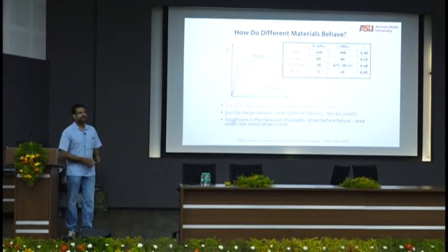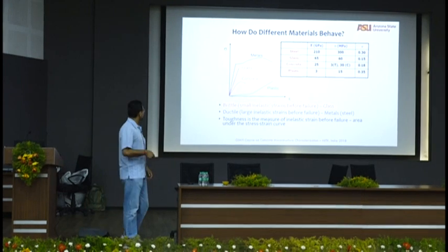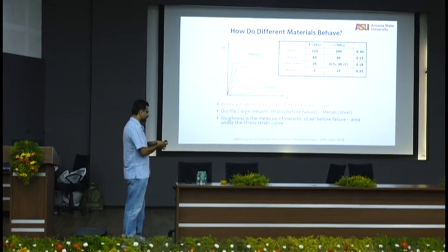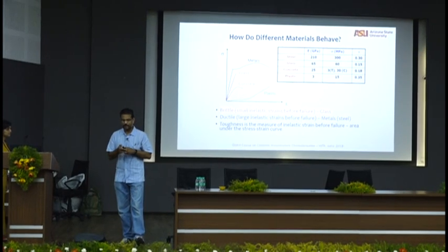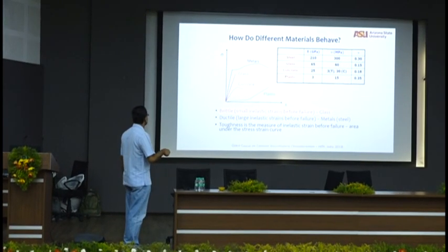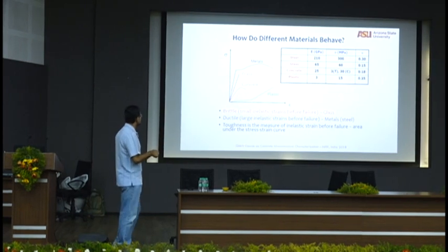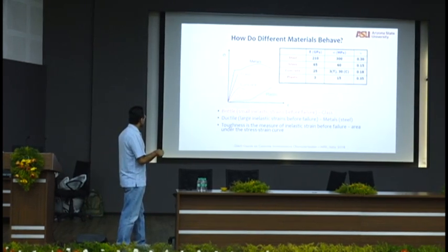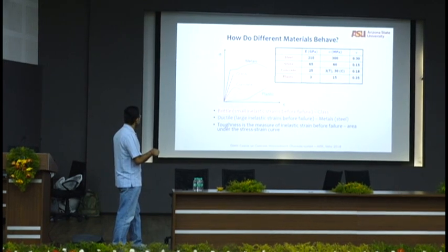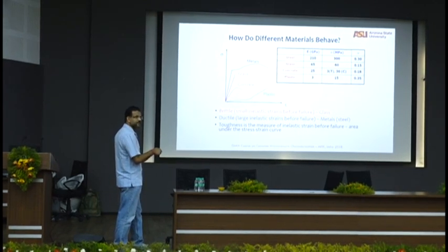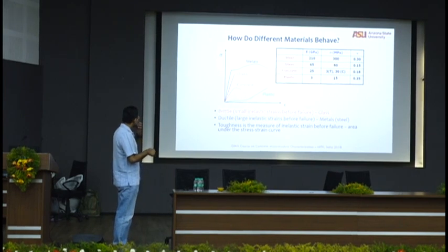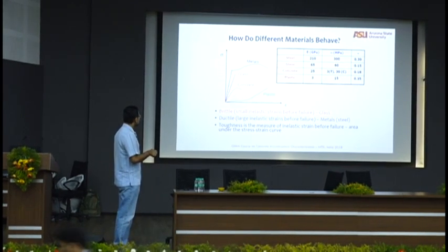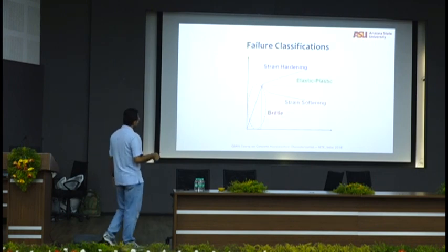We'll go to how different materials behave. If you do a simple stress strain curve, or maybe I have not switched this on. So it's my problem now. Okay. If you have different materials, if you have a metal, you know that you have a very high area of linear elastic nature, then you have yielding, and then you see the stress strain curve of steel, right? Glass, very brittle. Concrete, kind of quasi brittle. Plastic, viscoelastic, and then you have some elastic modulus and maximum compressive and tensile strength values, and Poisson's ratio for all of that. You can have different types of concrete.